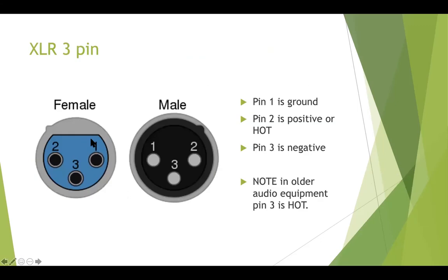So some miscellany. Let's talk about the XLR connector. Pin 2, remember I said before that microphone pin 2 is positive. So pin 2 is always hot. If you're ever doing any repairs on a microphone or a microphone cable, pin 2 is always the positive signal. Pin 1 is the ground and pin 3 is the negative, okay?